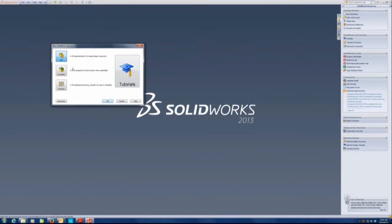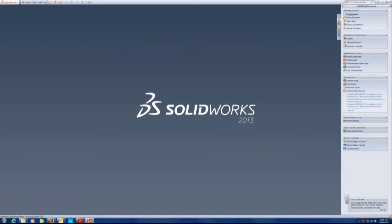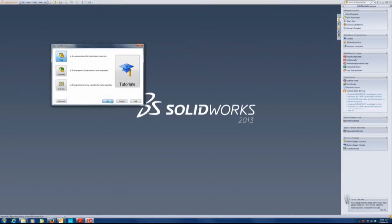Now, just on this quickly before I click OK, there are 3 modes that SolidWorks can go into. The first is Part mode, the second is Assembly mode, and the last is Drawing mode. The workflow in SolidWorks is you draw parts, lots of parts, one by one, and save each part individually in a folder. Then we assemble all those parts together in an assembly. That's where Assembly mode comes in. And then lastly, we make drawings of either the part or the assembly. And that's where Drawing mode comes in. But for now, we're just going to use Part mode. So just to revise there, I clicked on New Document, Part, and I'm going to say OK.